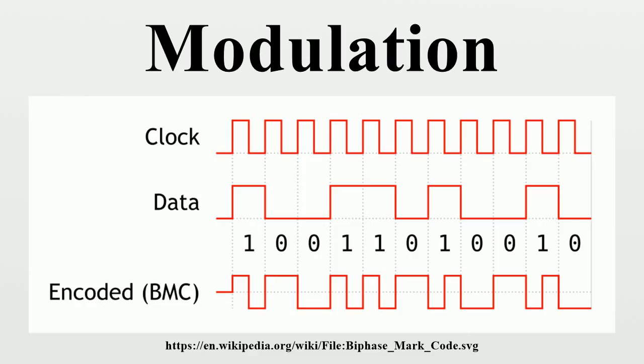The aim of digital baseband modulation methods, also known as line coding, is to transfer a digital bit stream over a baseband channel, typically a non-filtered copper wire such as a serial bus or a wired local area network. The aim of pulse modulation methods is to transfer a narrowband analog signal, for example a phone call, over a wideband baseband channel or, in some of the schemes, as a bit stream over another digital transmission system.